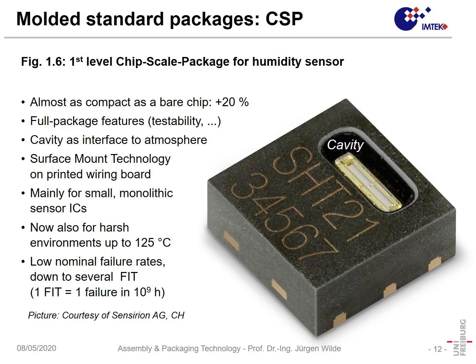And 1 FIT is 1 failure in 10 to the power of 9 hours times sample. So that means you can take 1 billion devices and test them for 1 hour, or you take 1,000 samples and test them for 1 million hours, or you take 1 million samples and test them for 1,000 hours.